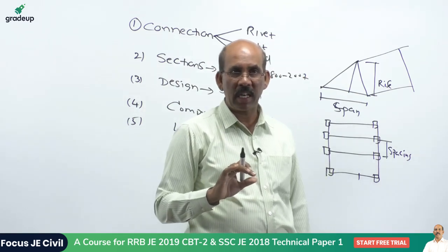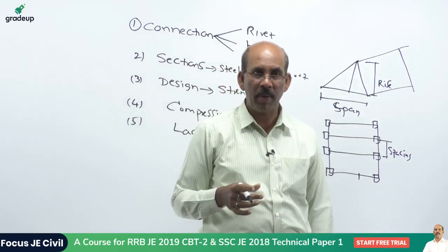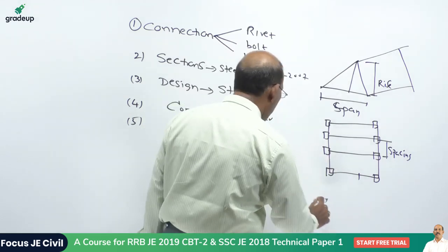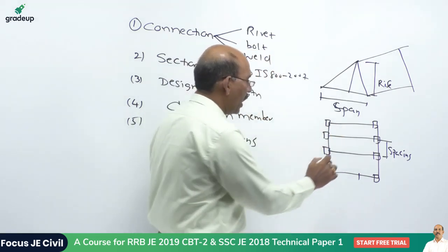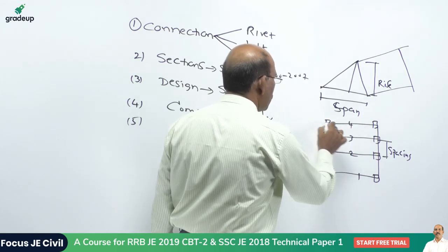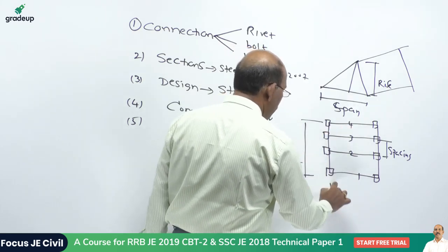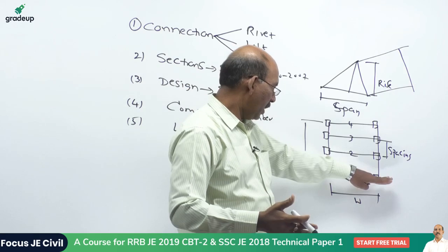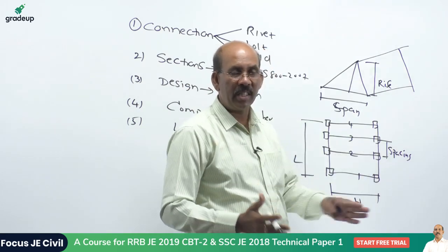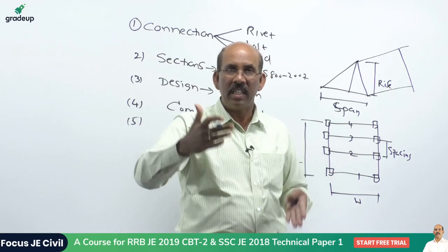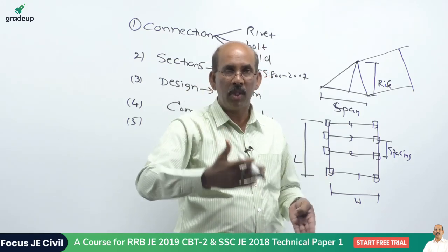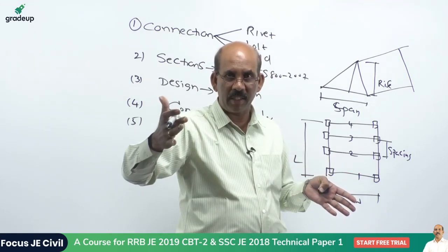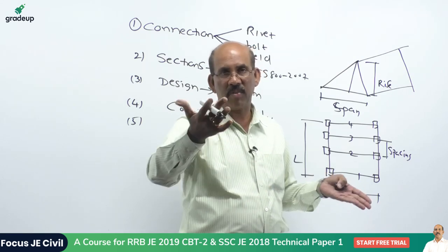Mr. Tushar Chandar, what is economical spacing? It's a very good question as you mentioned here. So as far as here you mentioned the trusses which you are going to place one behind the other. So suppose this is the length of the building and this is the width of the building. As far as your economic spacing means, the space which you decided here is made in such a way that the cost of construction should be minimum. So the cost of construction is based on your spacing. If you go for more number of trusses rather than less here, cost of construction will be more.